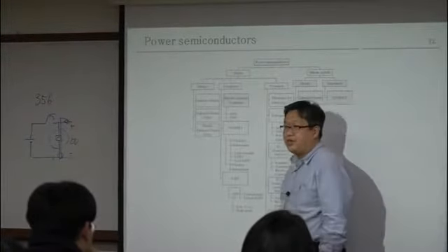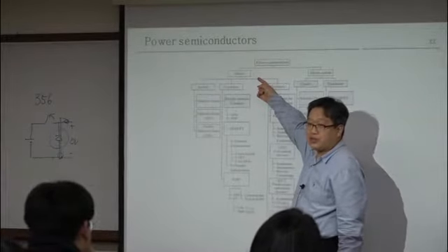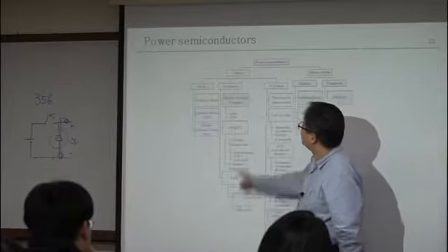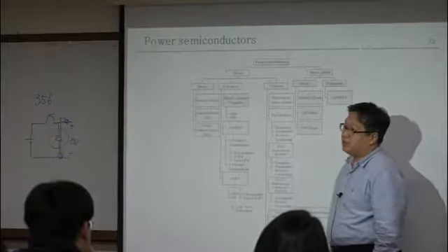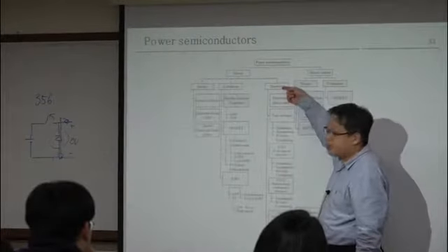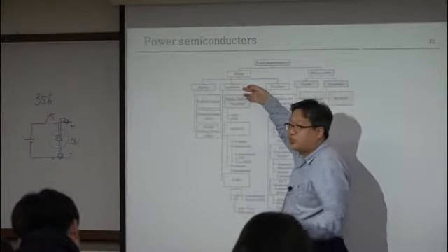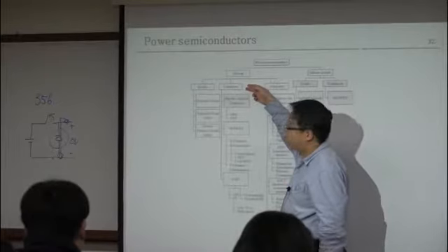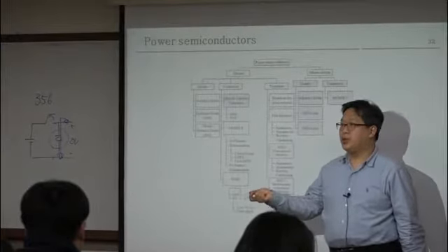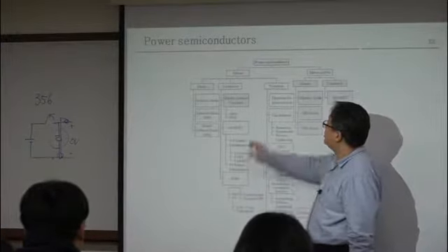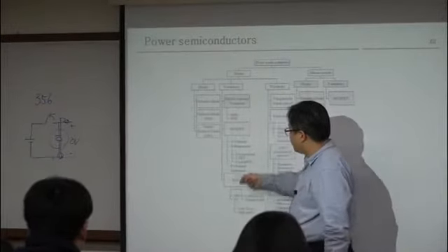Okay, typically we have used silicon as the material for power semiconductors, such as diodes, transistors, and thyristors. In the early 1960s, they used thyristors, but after transistor technology matured, mostly we use transistors to implement the switching circuit, because turn on and turn off control is much easier for the transistor than for the thyristor. Here, for transistors, you have several kinds of transistor.